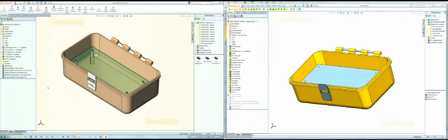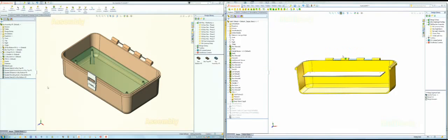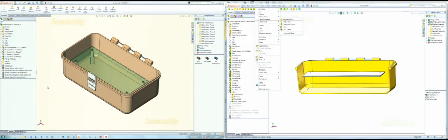So we've inserted it the same way we used before, with the constraints. But we don't have any standoffs to hold it yet. We don't have any mounting bosses, okay? So that's the next thing we've got to do. We've got to put a mounting boss in this. So that's another fastening feature.